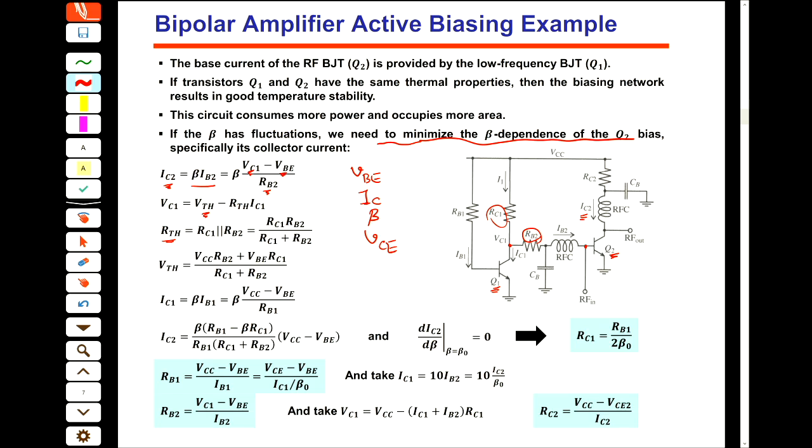Ask some question. Okay, that was the first lecture. Here, if we look at the I stage, it's like the 1 over GM in parallel with the RO. I want to ask, I think this one is just an RO. So which RO is this? Is it the output resistor for this transistor, or this transistor? Just this transistor.